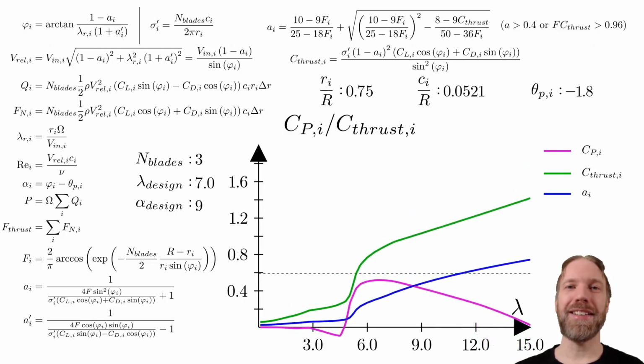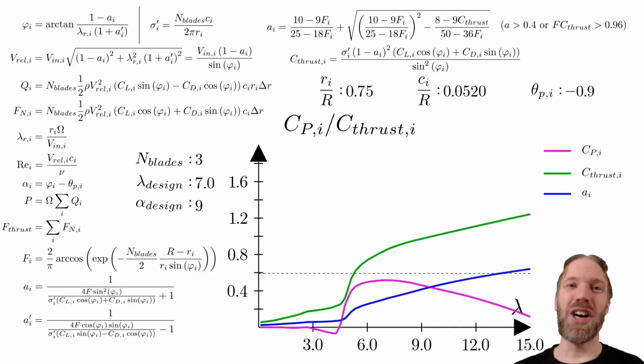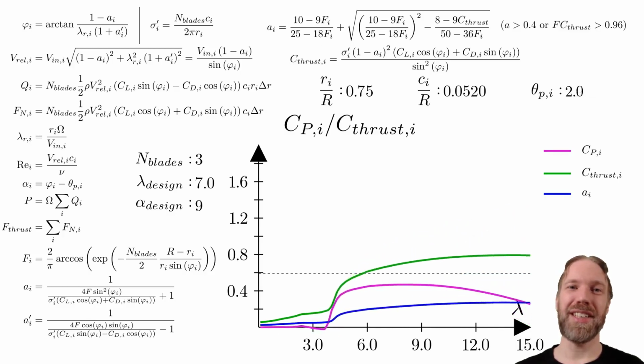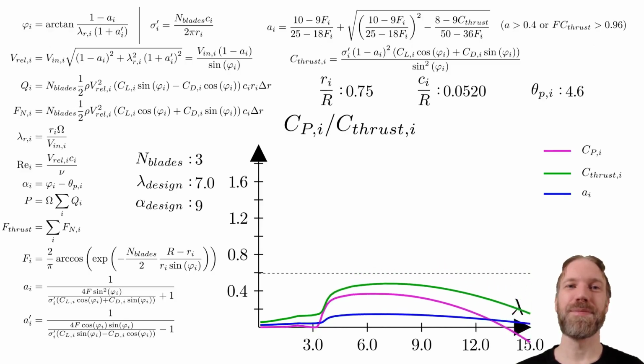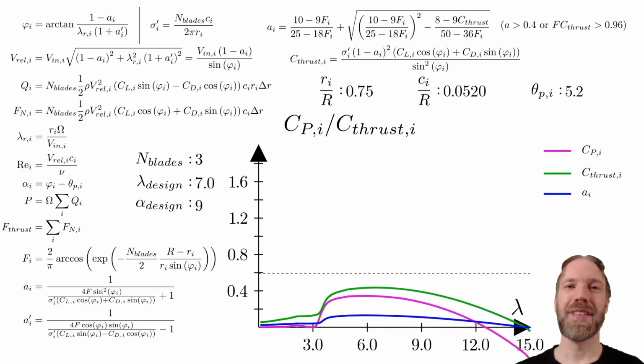Now we're going to test and change the pitch angle to illustrate power control. First, let us test pitch to feather and decrease the angle of attack. This initially moves the peak power coefficient to slightly larger values. Note how both the power and the thrust force decrease. Let us return to the base position.